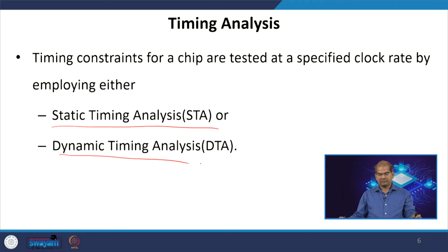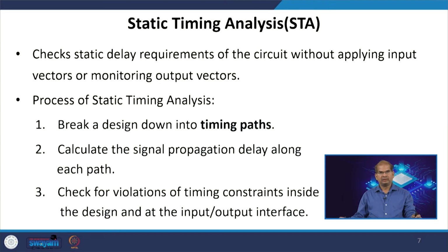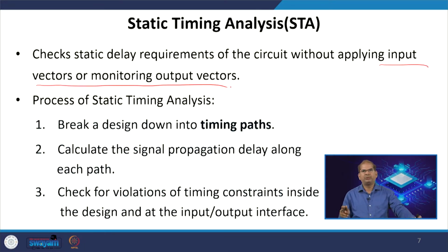Static timing analysis is the timing analysis methodology in which we do the timing analysis of the circuit without applying any input vectors and also without monitoring the output vectors. So, static means that no input is supplied to the timing analysis tool.